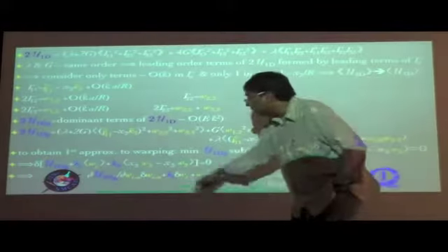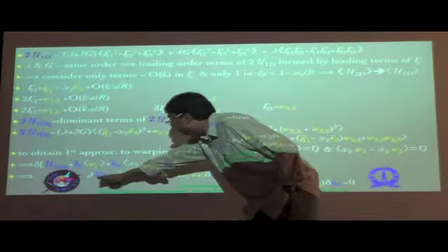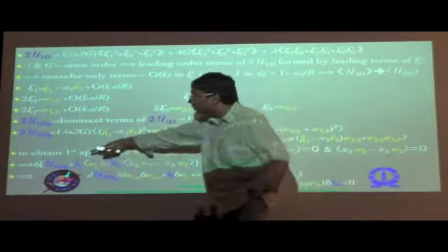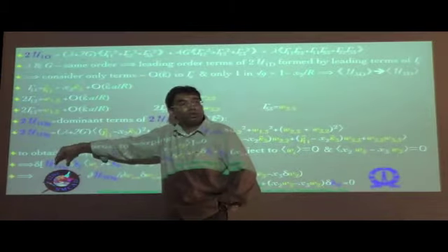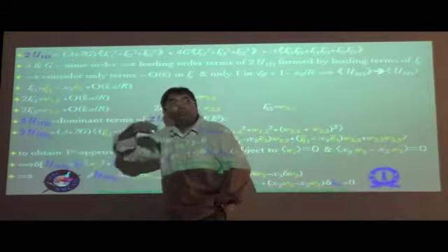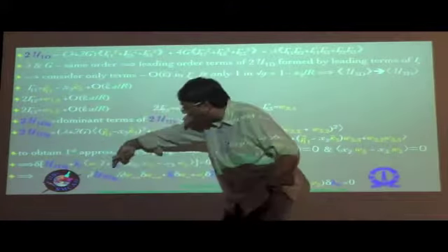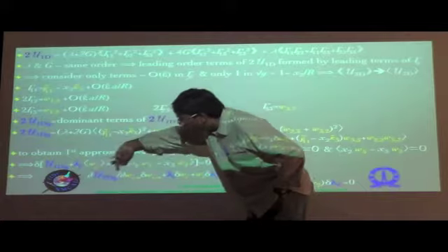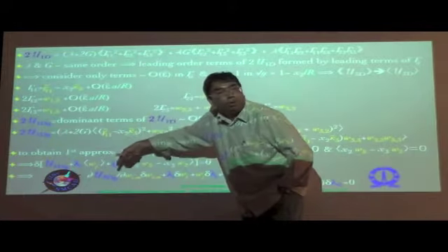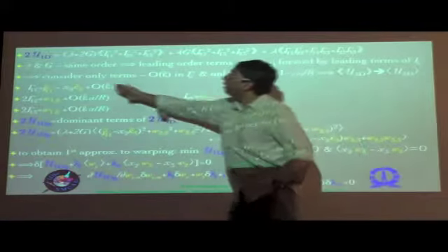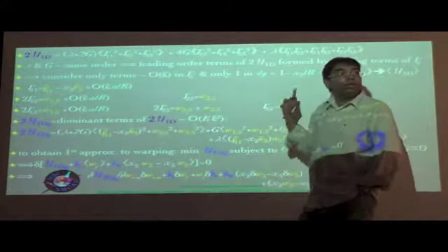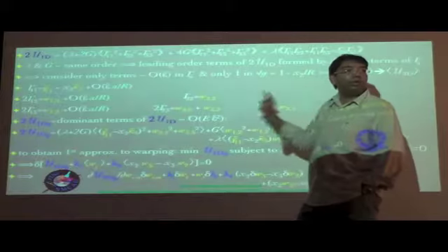Next, we can expand that out. So basically, you have the partial derivative, because remember that U1D naught is an integral over the cross section of those of U3D, of course with the root g also involved, and therefore you would have the partial derivatives of U3D, because the unknown quantities are the warping, and they all appear as derivatives. Anywhere you see in the leading order terms, you don't see w1, w2, w3 appearing by themselves.